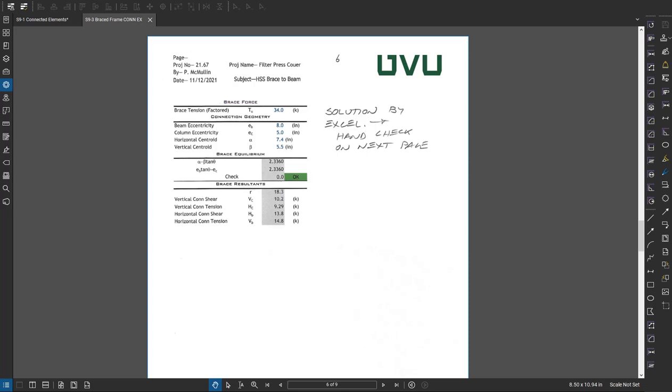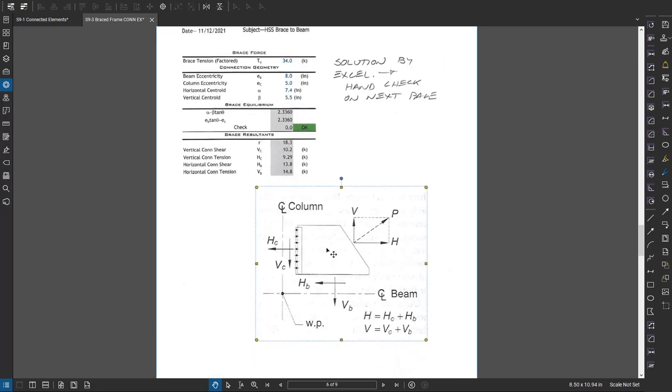So I pulled those into the example. At each interface where the gusset touches either the beam or the column, we have the forces for those. Typically we weld to the beam, so the beam comes out with a gusset on. We bolt to the column. That's far easier than trying to swing the beam in, plus column flanges tend to be fatter, so they're easier to bolt to.